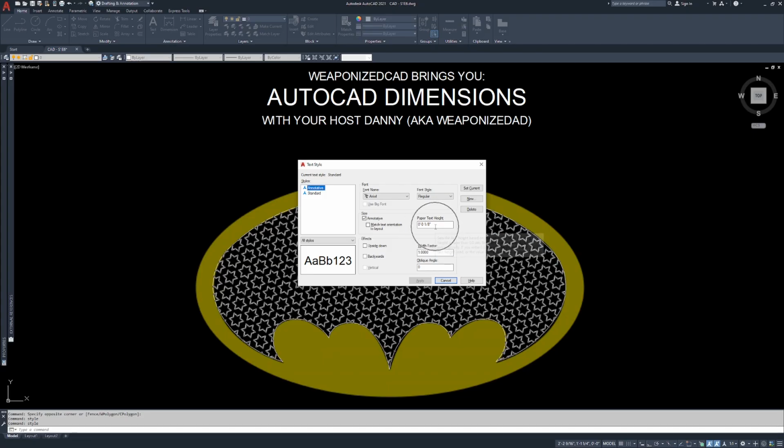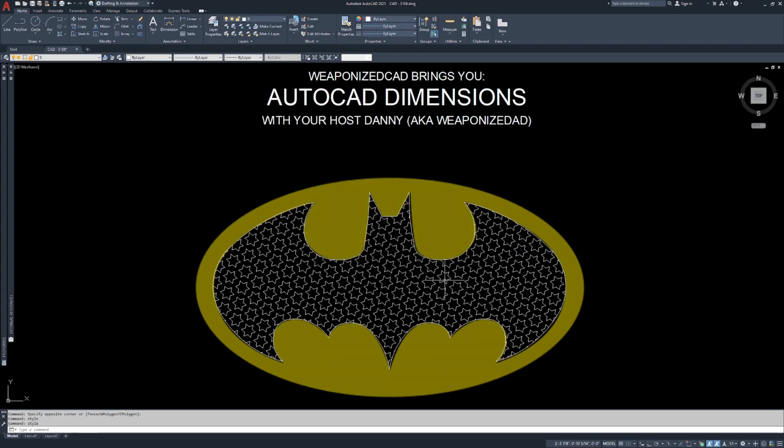So set that to 1/8 of an inch, set this to annotative. Leave this unchecked. This is sketchy, and it's only used in certain cases. Right now, we don't want to use it. Match text orientation and layout, we don't want to touch that right now. So I already hit apply. I had to jump back into style to check it. I'm going to click cancel because that's done, and we're going to go into dim style now.